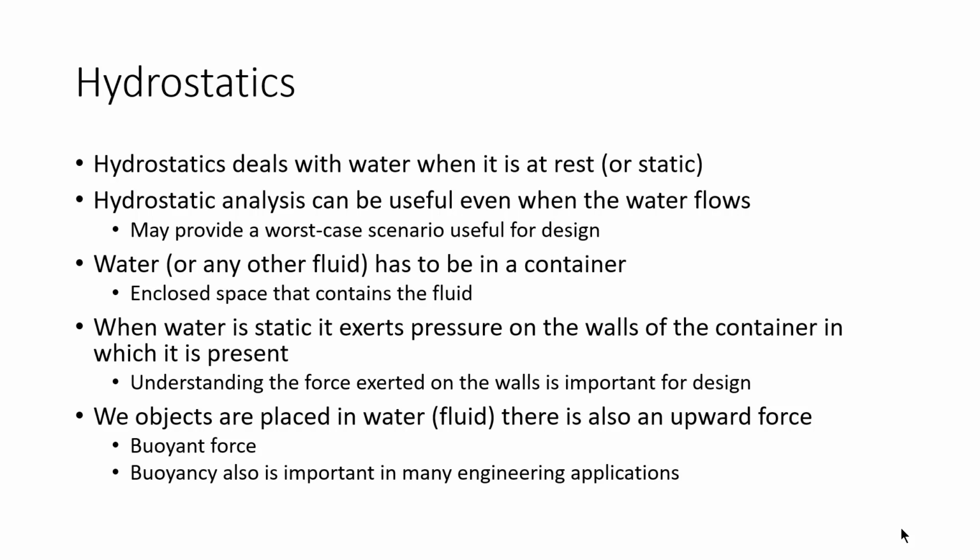Hydrostatic analysis is not only useful when we have water at rest, but we also use it even when the water flows. That's because hydrostatic conditions sometimes can give us a worst case scenario, which is useful for design. For example, the water in a reservoir could move up and down, or there could be flow in and out of the reservoir, but assuming that the water is there at a certain height helps us design that structure. So we often design assuming that there is stagnant water at a certain height when we're designing a reservoir.